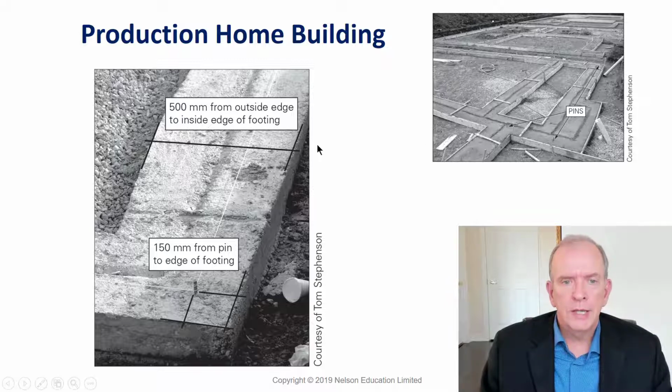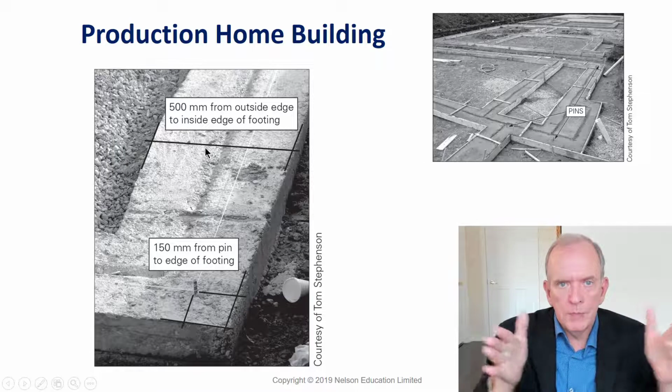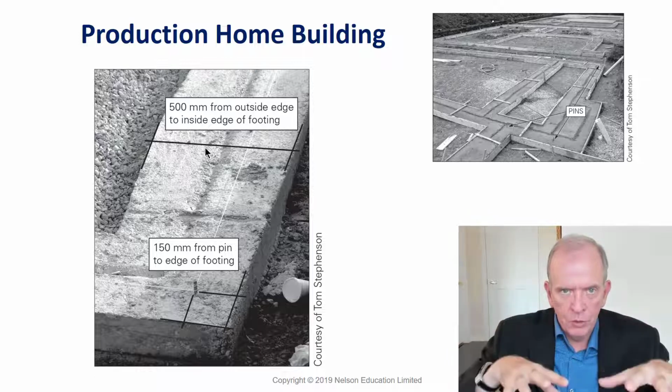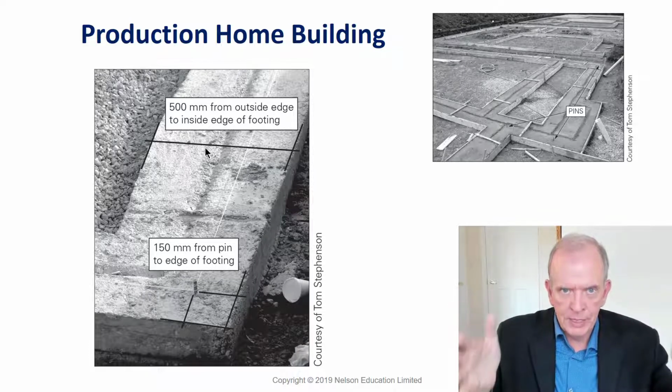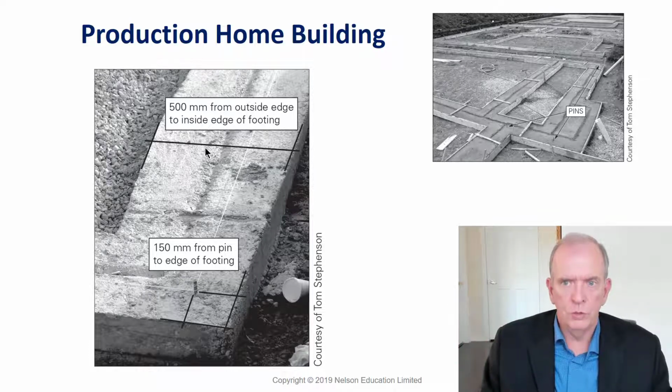So the footings, as I said, are wider than the foundation wall because they have to distribute the load that's being placed on them outwardly. And so they're going to be larger so that for the bearing capacity of soil, it's easier for that to carry that load.